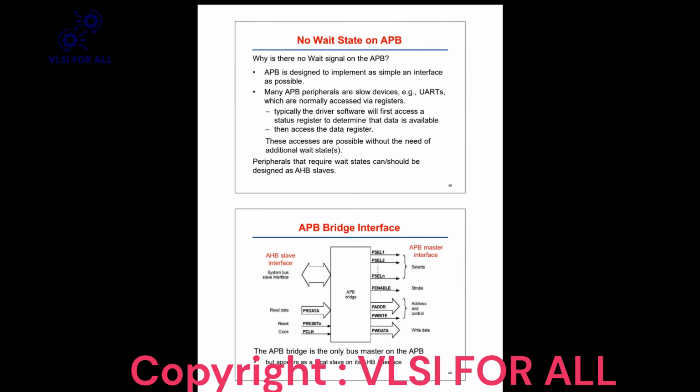No wait state is an earlier concept. So focus on the ready signal, you have to wait. If ready is 1, then you can do your transaction. If ready is 0, then you have to wait till the time the slave gets ready.